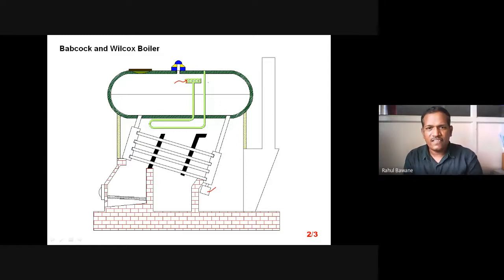But boiler accessories are meant for enhancing the boiler output, just like a superheater. If there is no superheater, then also the boiler will work and generate steam. The case is that we don't get that much output from that steam. To increase that output, we are using a superheater. That means without a superheater, there is not a big issue. You can't say that without a superheater, I can't run the boiler. No, you can run it. Only the efficiency will be lower.